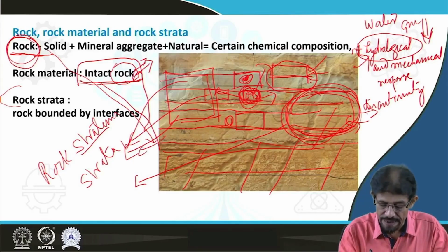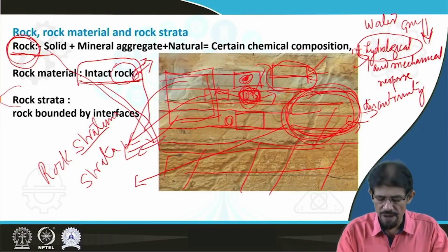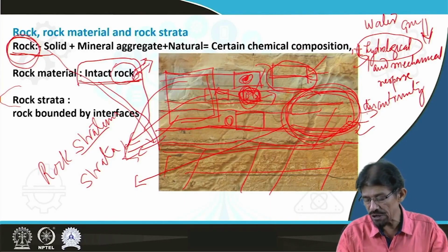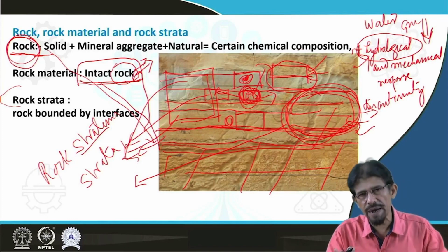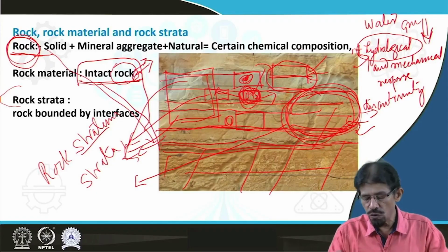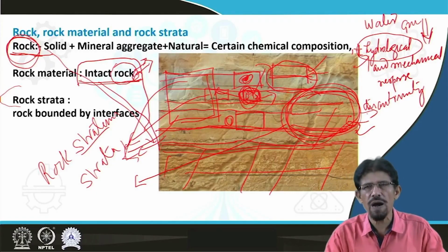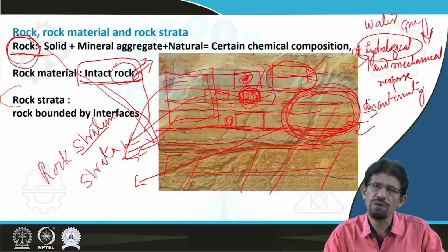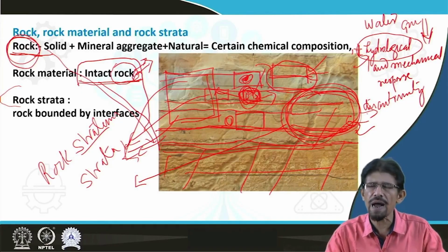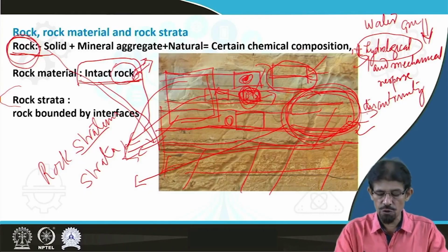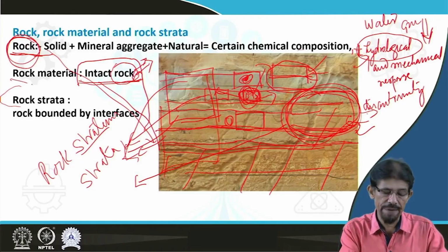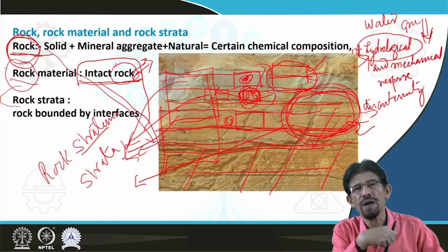But for our engineering geological purpose, here we are recognizing this type of interface as discontinuity. So in view of continuum characterization, we can say that this zone is discontinuous in nature. If discontinuous in nature, then the mechanical or hydrological response of this zone is far different than the consideration of rock.